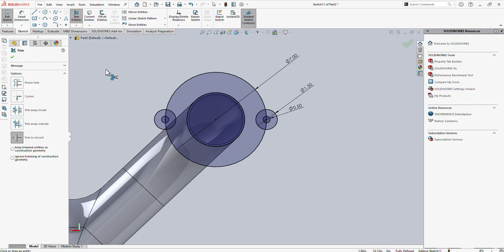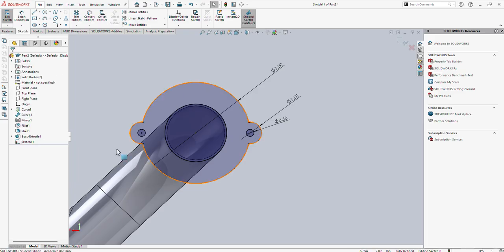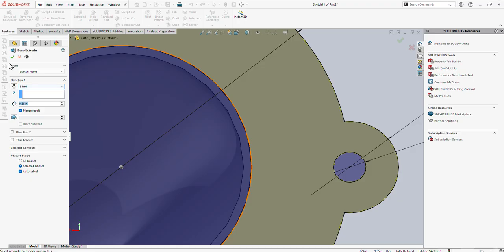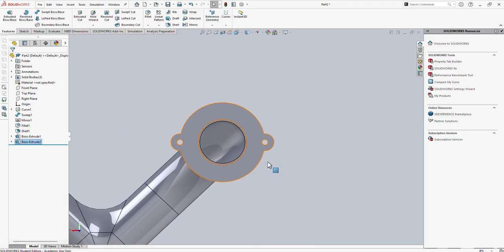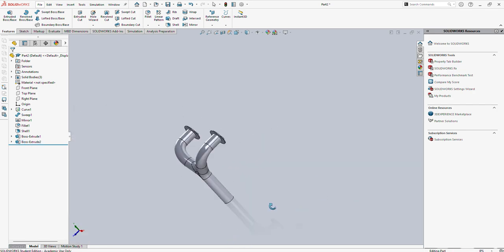Okay, using the trim tool, let's make it as one object, one sketch. Okay, cool, we're done. Extrude base, and we're doing the same thing, 1/4 inch and outer edge, done. So this is our exhaust joining bracket for the engine bay is done.